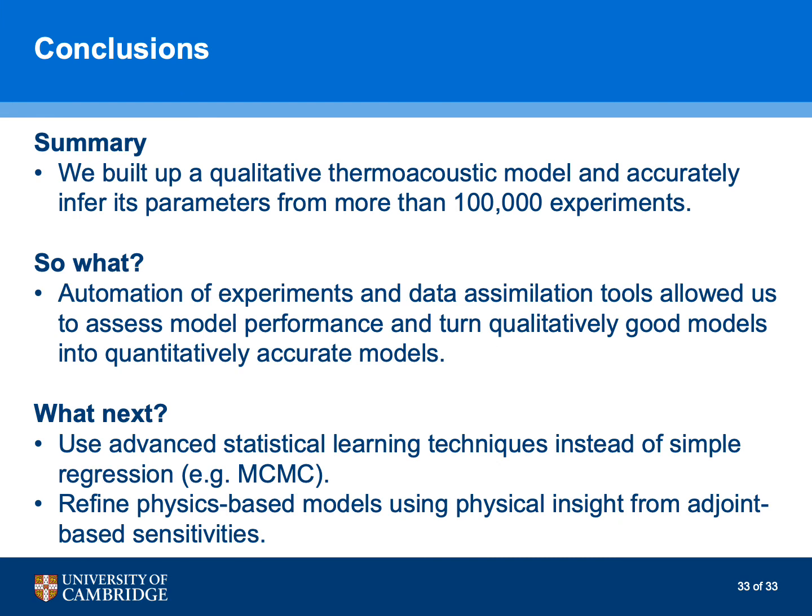This brings me to the conclusions of this work. So what did we do? We built a reduced order thermoacoustic model in a step-by-step fashion, using physical principles and training it using more than 100,000 experiments. We saw that by automating a laboratory rig, you can perform thousands of different experiments which can be used in conjunction with data simulation tools in order to build faithful models.